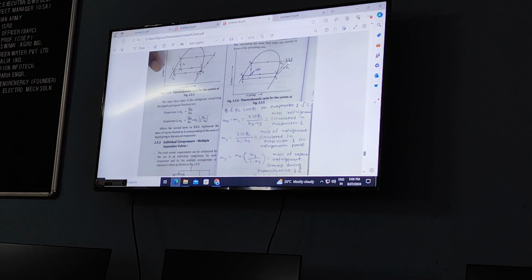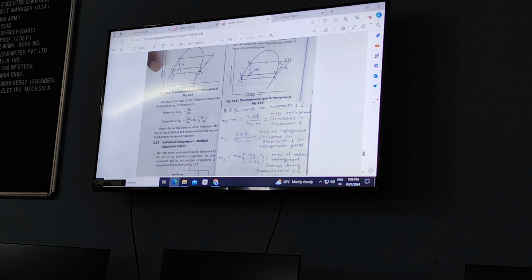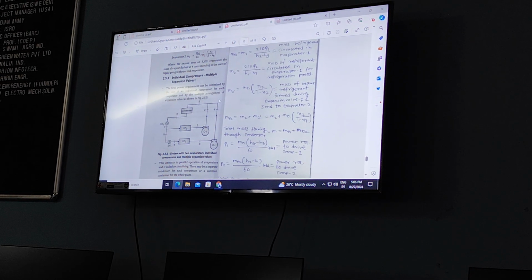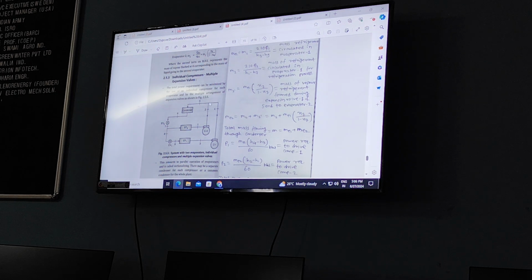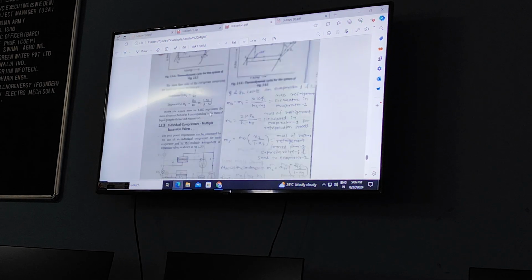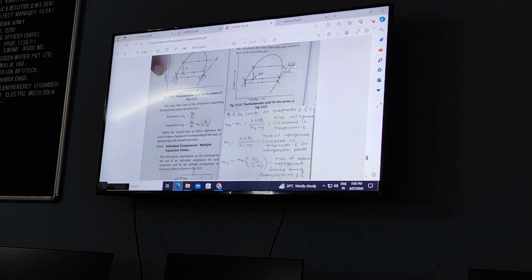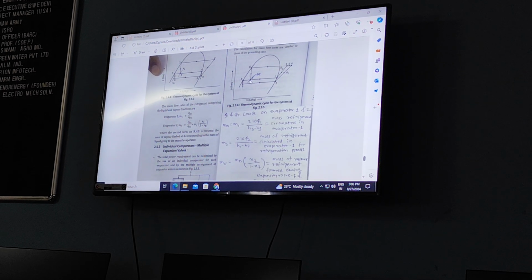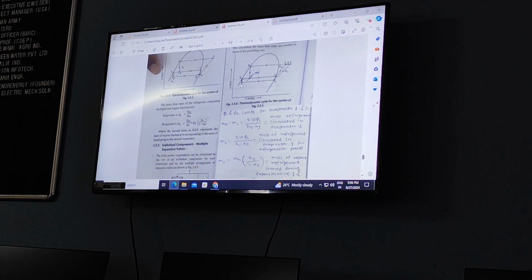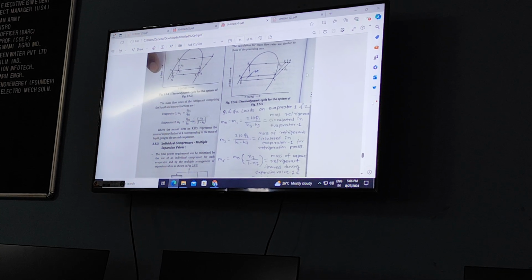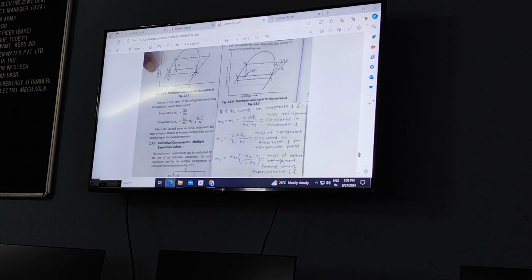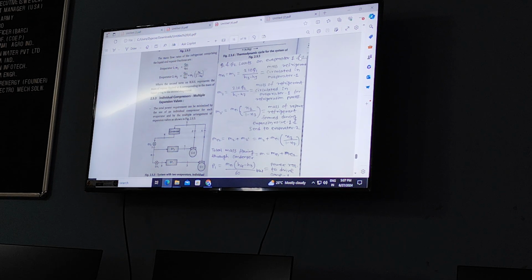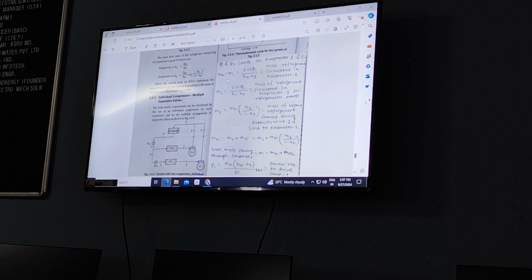Then now in individual compression, both compressor outputs have the same pressure. And then these are sent to the condenser from here. Then these are sent to the condenser here. Then 6 to 7 expansion, then second expansion and evaporation. And cycle repeats. Right? Here you have to write what is Q1 and Q2, loads on evaporator 1 and 2.